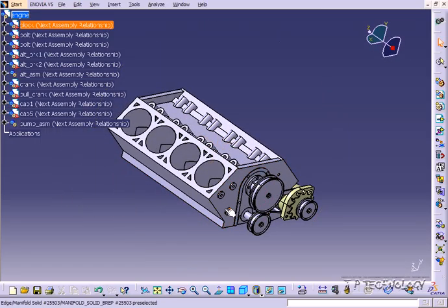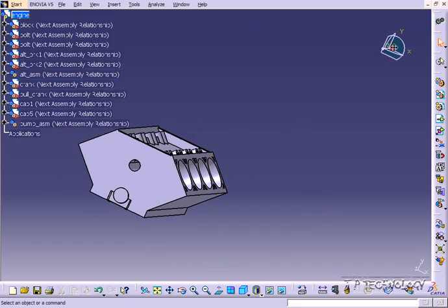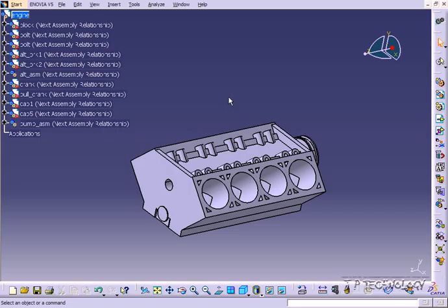And again, I can't emphasize exactly how important this is, because if I didn't have an axis there, when you try to throw it in there, you're going to get different results every time. To be precise and consistent every time, create the axis that you want to rotate about. You can use an edge too, but if you want to rotate through, say, a circle, get that center circle's axis in there and rotate about that.